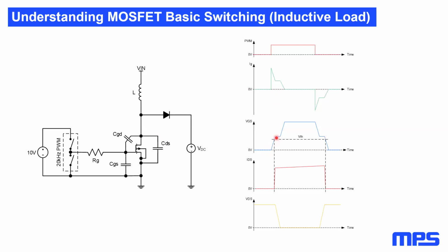Only a small current is flowing through the CGD capacitor. As the voltage increases at the gate terminal, the CGD capacitor voltage has to be slightly reduced. This period is called the turn-on delay, because both the drain current and the drain voltage of the device remain unchanged.